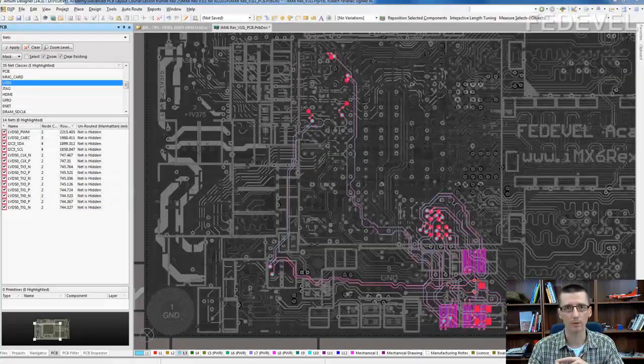What are you going to do then? You can, for example, go on the internet and try to find something similar, or a design guide which will describe the length matching requirements which you need to know. Or the easier, simpler, faster way to do it is just length match these interfaces within 10 mils.